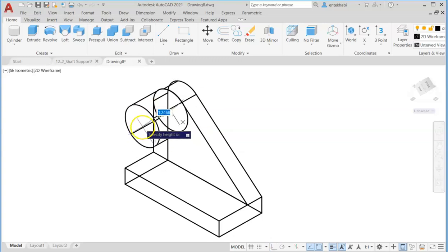And the height or z-axis direction also would be 0.75. If you subtract 1.38 from 1.38 minus 0.63, that should be 0.75. And I'm going to union these two also at this time.